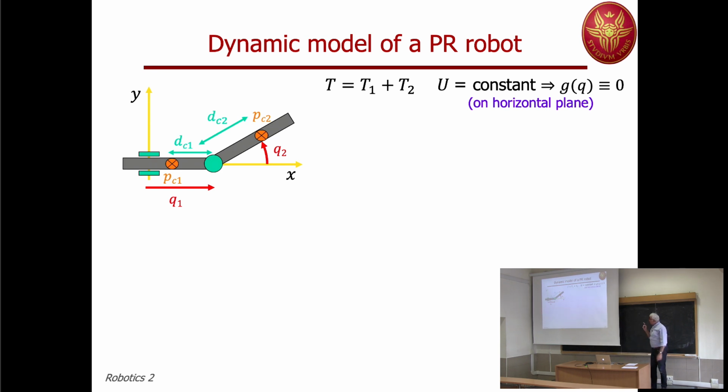Now, one warning here: x and y are not x0 and y0 of a Denavit-Hartenberg notation. Because in this case, z0, the only thing that is being fixed, should be along the first joint axis, and the first joint axis is this prismatic one, so this should be the z0 axis, while here I've labeled it as x, because we are on a plane, so it's natural to consider the two coordinates x and y.